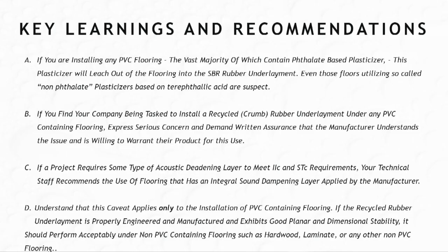I don't know. Now, this is key: if you find your company being tasked to install a recycled crumb rubber underlayment under any PVC containing floor, express serious concern and demand written assurance that the manufacturer understands the issue and is willing to warrant their product for this use.